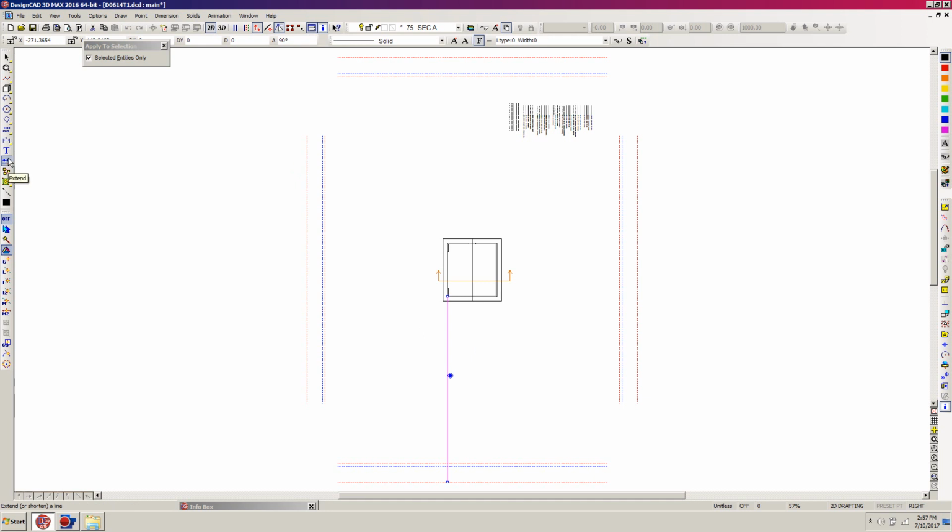It's also over here in the line tool, and I'm going to just left click near it and bring it on down. You can see that the line is wanting to move. I can actually extend it further or bring it back down. I want to get it down to the ceiling line, which is the other upper red line here. And I'm going to get close to that ceiling line. Then I'm going to hit K. And you can see that the outside wall line now goes from the ceiling to the floor at this point. And it's still selected.